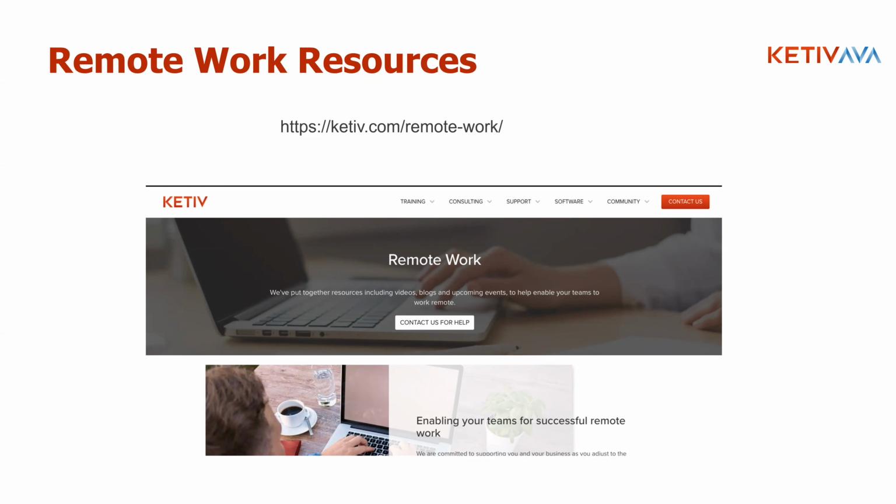I've actually done LINQ queries in iLogic, and they work. As a matter of fact, I've had some customers after my last AVA where I showed that say that they have started using those and actually have found that it's sped up some code by doing that, which honestly surprised me. But since you can do LINQ queries, I believe you should be able to do lambdas. If you know how to do LINQ queries, it can really be a godsend, especially if you're doing complicated stuff in iLogic or in the API.